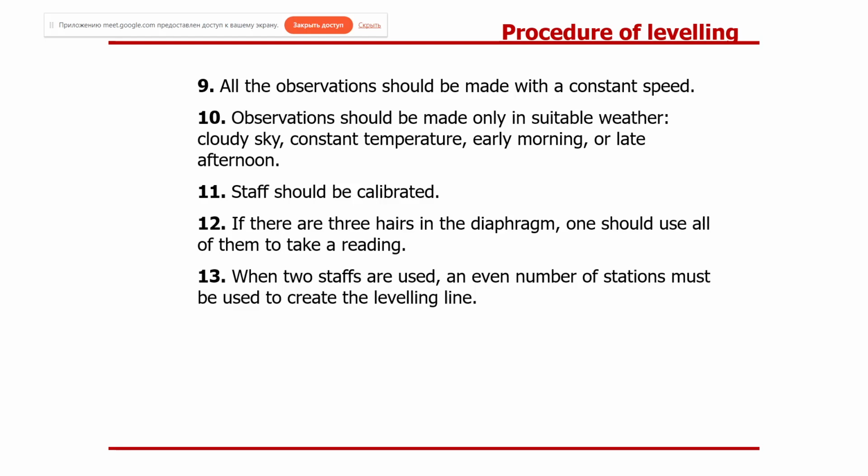Observations should be made only in suitable weather. Well, a cloudy sky, constant temperature, early morning or late afternoon.